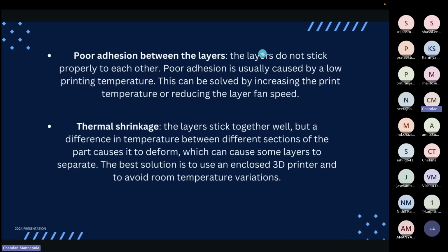So, poor adhesion between the layers. The layers do not stick properly to each other. Poor adhesion is usually caused by a low printing temperature. This can be solved by increasing the print temperature or reducing the layer fan speed.